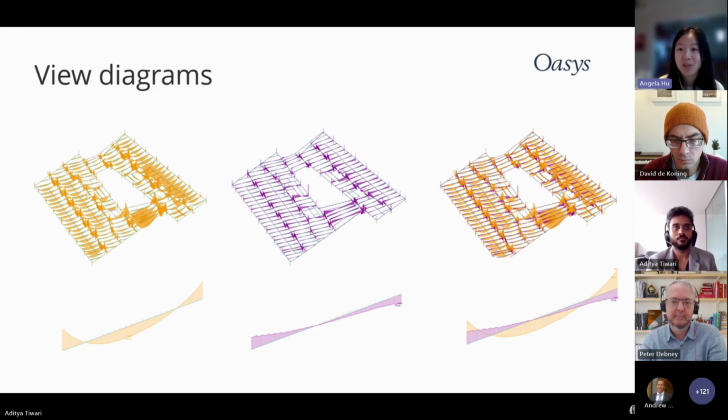But in reality, what you could do is that you could put the loading diagram on top of that, you could put the axial force diagram on top of that, you can even put in a contour as well. And it really allows you to see what is going on in the structure because you can see how each component interacts. Does this shear diagram make sense with this moment diagram? You can ask these questions and see them all together at once.